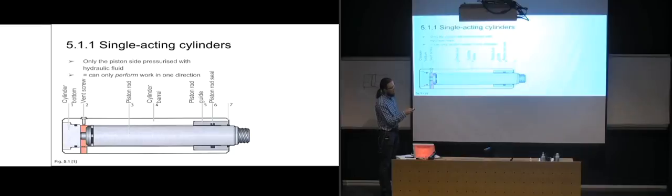And of course you're going to have a seal on the piston, and you have to have this wiper ring on the tip in order to avoid too much debris and dust being pulled back into the cylinder. Because if you didn't have the wiper gathering up all of the dust and foreign particles, they would have been pulled in here, and then they would have hit the seal, and they would have created damage on the seal, at least fairly large, sharp dust particles. It would destroy the seal pretty quickly.